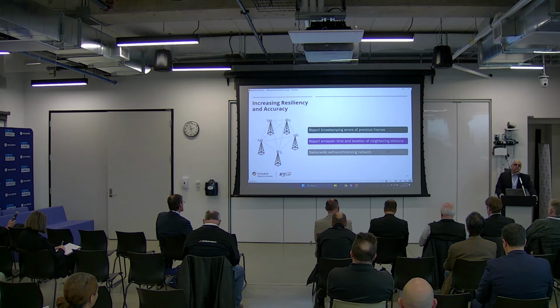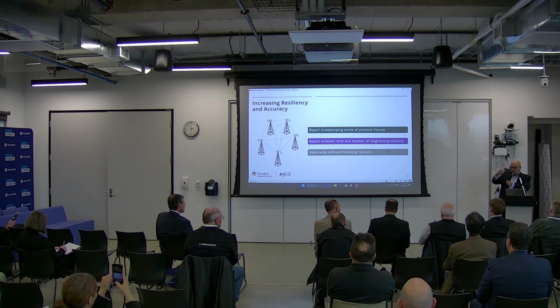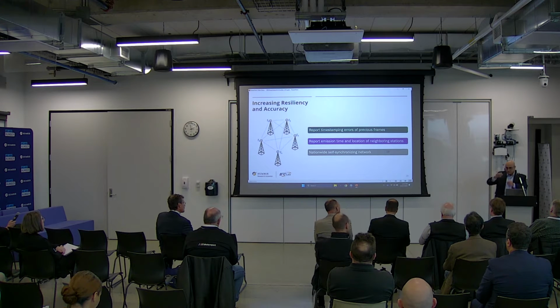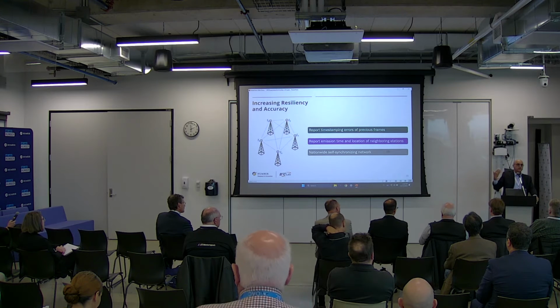In terms of future improvement, so far we have talked about what we have done, but I think there's room to improve the system. The first one is, as we are timestamping, we get the timestamping error, and we are synchronizing the loop. That's totally fine. But the receiver that has received the signal, say the timestamping error was 5 nanoseconds, will have that 5 nanosecond error in there.